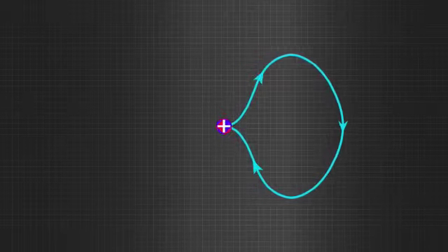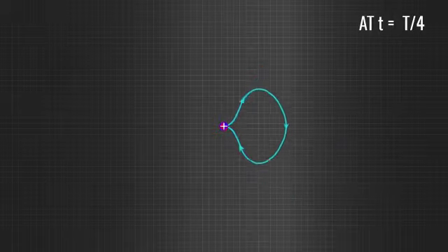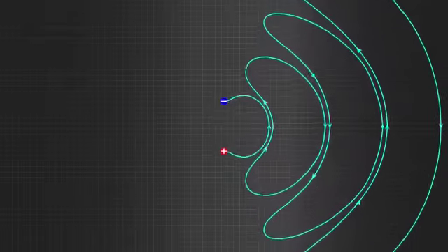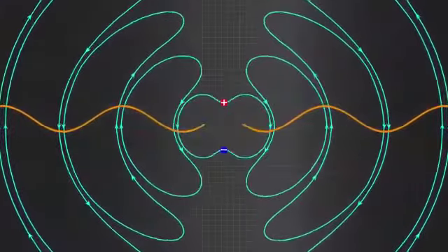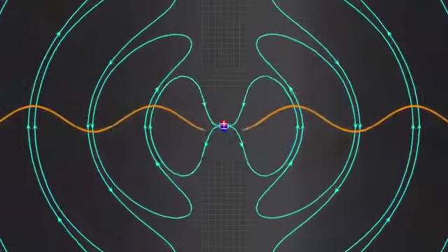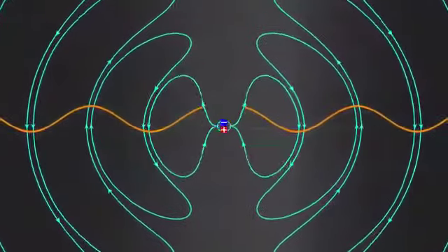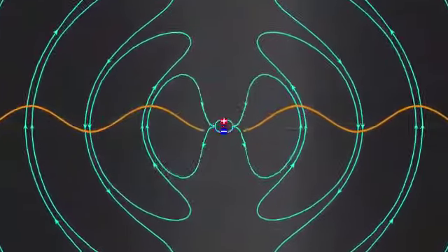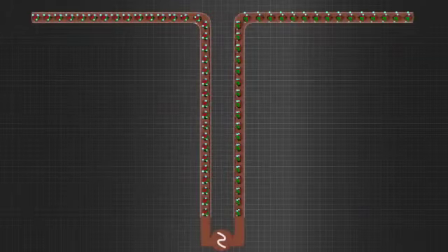When 2 charges meet at the central point, the deformed line also meets there. After that, it detaches and radiates. This radiation travels at the speed of light. If you plot an electric field intensity variation with respect to length, you can see that the radiation we have produced is perfectly sinusoidal in nature. Please note that this varying electric field will automatically generate a varying magnetic field perpendicular to it. Now, let's have a look at how this applies to an antenna.